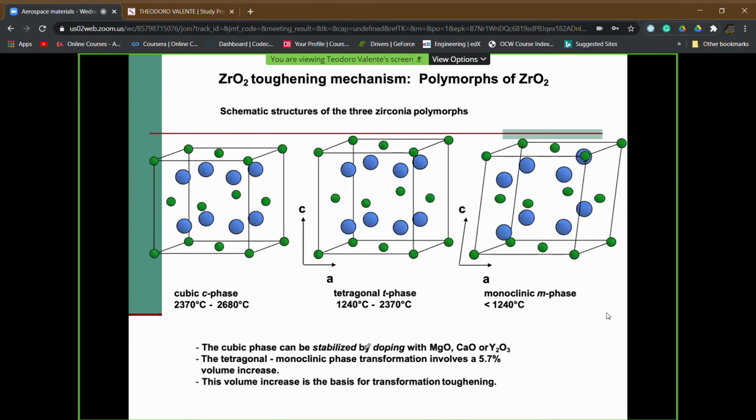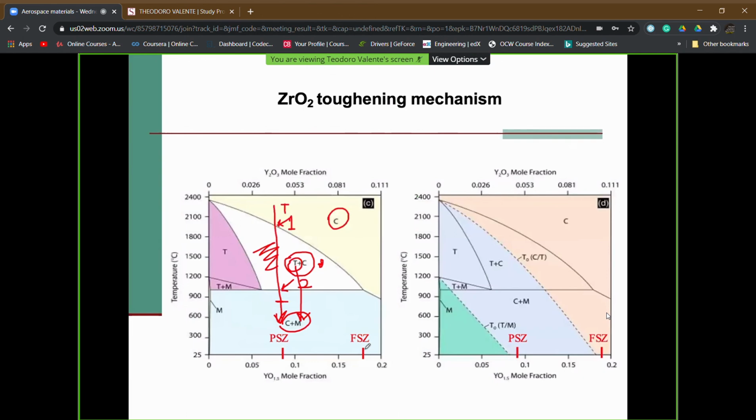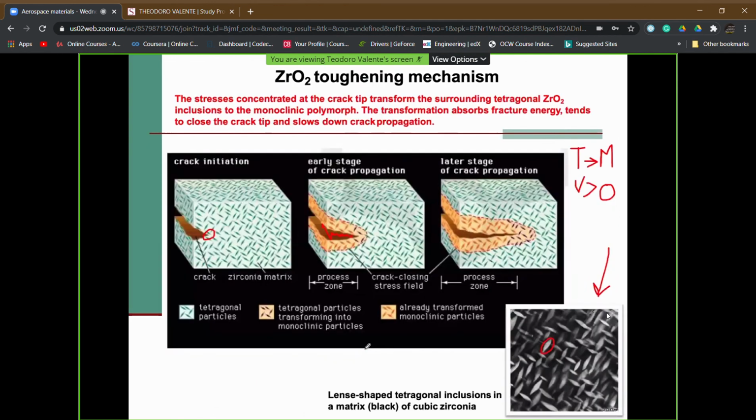So these are the reasons why we use these ceramic materials in our solution of thermal barrier coating, relying on a toughening mechanism induced by stress, thanks to the possibility to fabricate the top coat having a stable cubic phase with a tetragonal metastable phase dispersed inside.